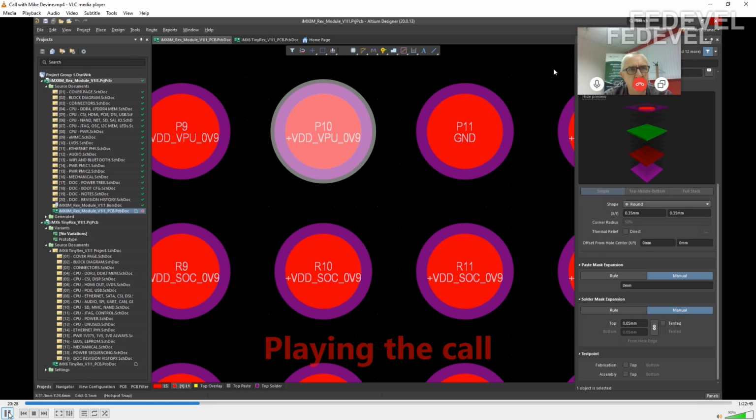But the only time that we have seen this as being a problem is mainly if you put the microvia directly on top of a buried via. Whether that buried via is copper filled or resin filled, under thermal constraints, i.e. the application of the board, if the chip is going to run very hot, it can cause the PCB to expand, and what can happen is you end up with what they call an eyebrow crack.